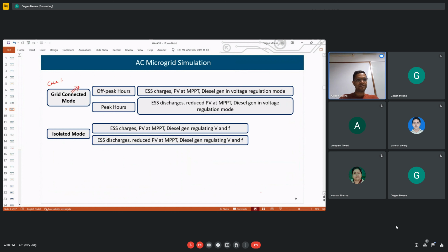Before starting that, CVC is coordinated voltage control, and its objective is to utilize all the available voltage regulating devices to increase the overall reactive power reserve, to keep the voltage within the nominal limits, and also reduce the post-fault voltage recovery time. Because during a fault, voltage dips.